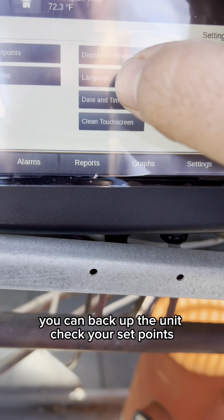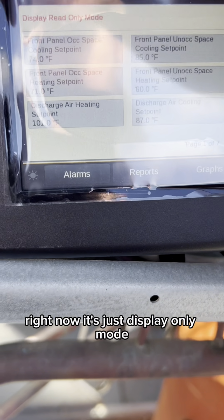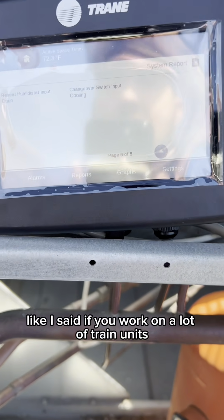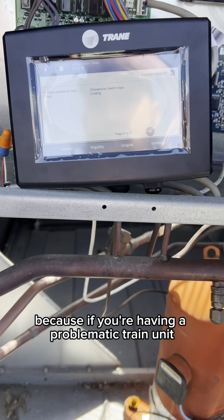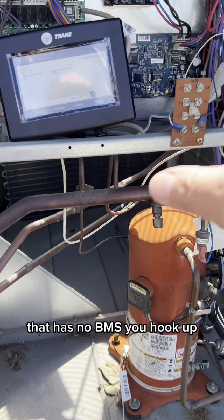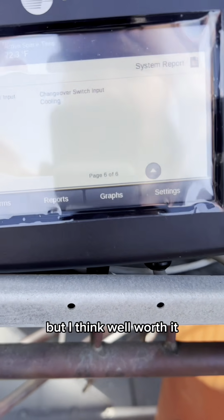You can back up the unit, check your set points. You can change set points from here. Right now it's just display only mode because we have a BMS hooked up. Like I said, if you work on a lot of Trane units, maybe think about picking one of these up, or have your company pick one up, because if you're having a problematic Trane unit that has no BMS, you hook up, you'll get a lot of information. They're about $800. They are a little pricey, I think well worth it.